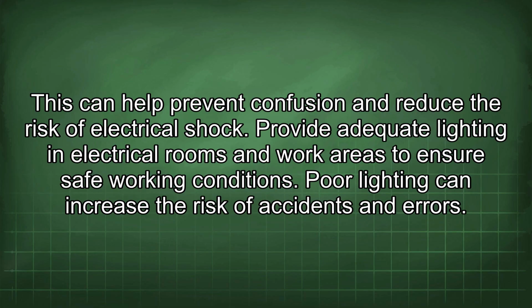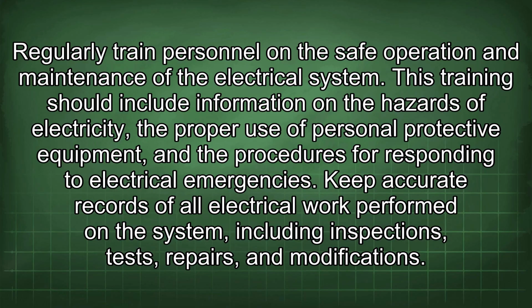Provide adequate lighting in electrical rooms and work areas to ensure safe working conditions. Poor lighting can increase the risk of accidents and errors. Regularly train personnel on the safe operation and maintenance of the electrical system. This training should include information on the hazards of electricity, the proper use of personal protective equipment, and the procedures for responding to electrical emergencies.